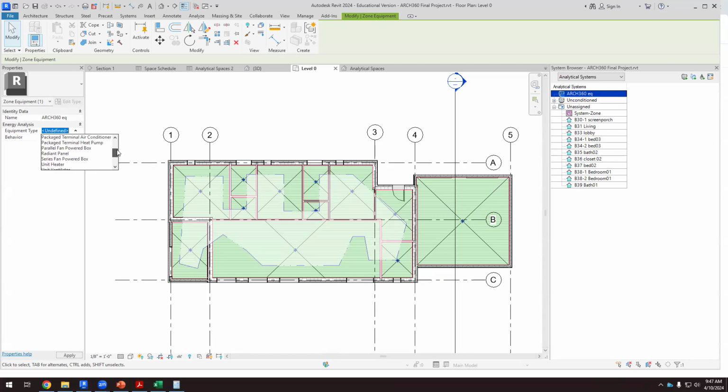So there are different options. So those are all the systems that we can create, we're going to work with a water source heat pump. The behavior is group spaces. We're going to group space, and the condenser water is undefined. Okay, why is it undefined?